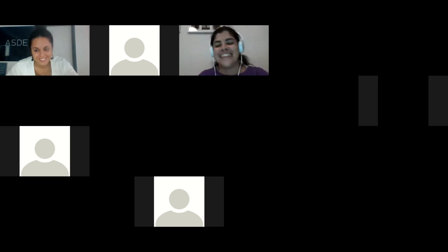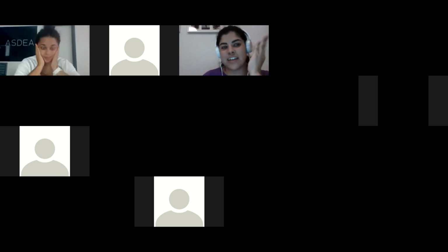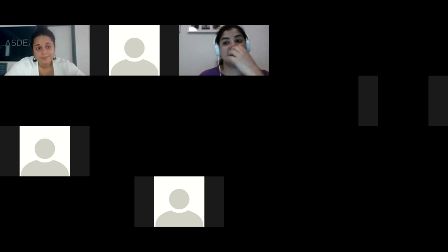Your mic is off. Yes, I ran into this problem like every 2 or 3 days. You have to either change the size of your element, or see if you don't have a mistake in the units of your fracture energy, which is why it's really small, and so you have to calibrate it until it runs. Normally, in my case, I always have 2 orders of magnitude less when I do all the conversions between newtons, kilonewtons, millimeters, and meters, and then after this it runs.